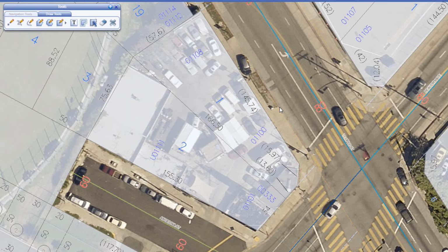The Draw Tools tab contains tools for adding or editing markups and text on the map. The Draw Point tool places a point on the map with a single click. By default, the point is drawn with an orange fill and a green outline. You can change the style by clicking on the Change Markup symbol icon, also known as a color palette.